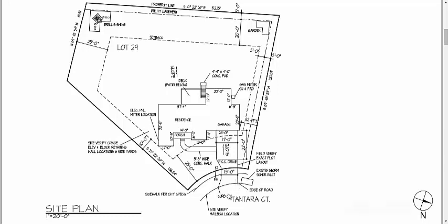The other thing that makes the driveway kind of complicated is you see this right here, it says existing storm sewer inlet. Now most codes say that the edge of that inlet, you have to be 1 foot minimum away from that before you can start your driveway. So this driveway was really squeezed. It was squeezed in between this inlet here and squeezed in between that manhole there. So some conditions you got to look out for.